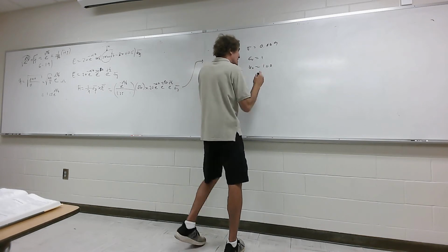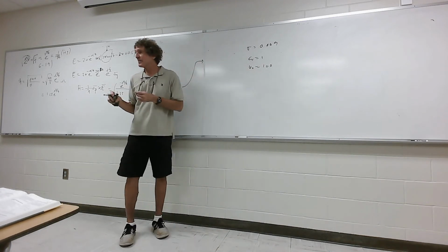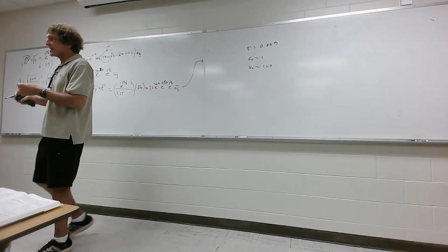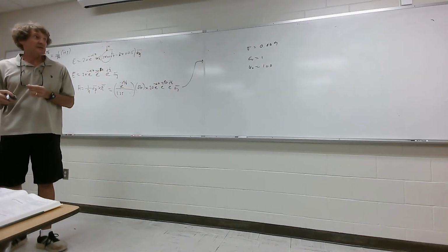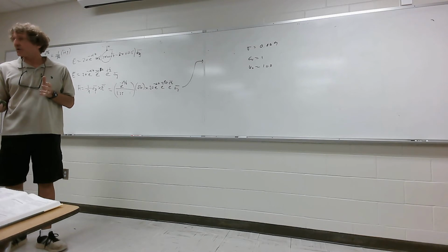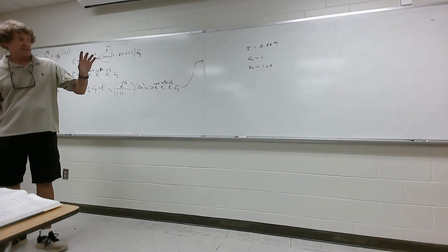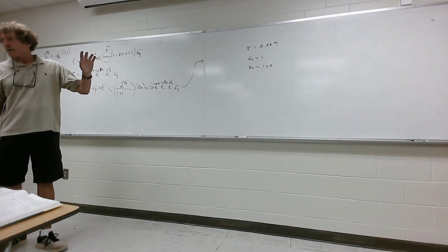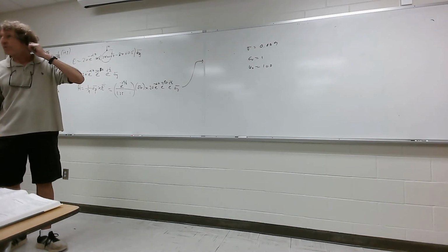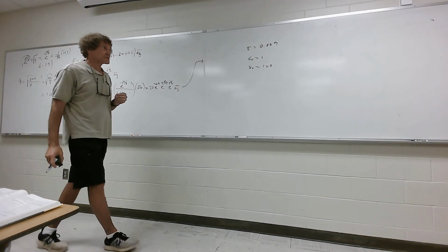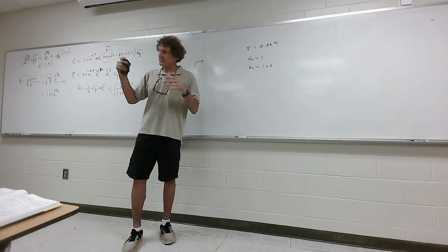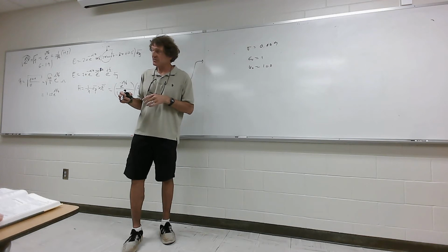I was just curious, what kind of material would that be? Magnetic. As a matter of fact, it's probably some sort of an iron. You know, when you use laminated iron for transformer cores, it's at a certain frequency, but wouldn't that have a greater conductivity? Well, the conductivity in pure iron is much, much greater, but you can add things to it to drop that conductivity to reduce the losses.